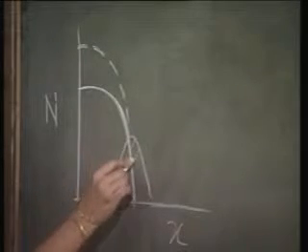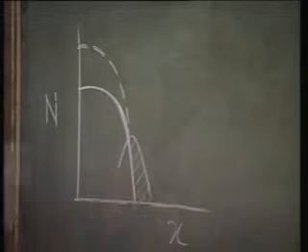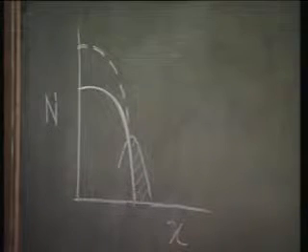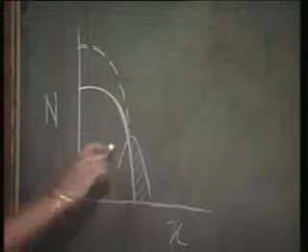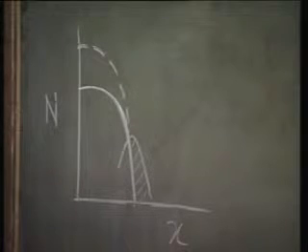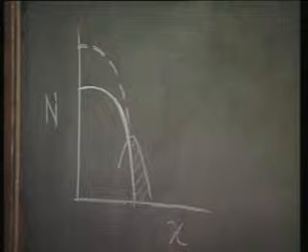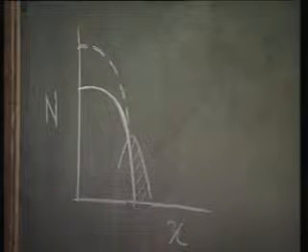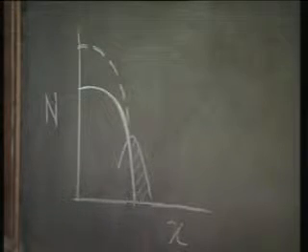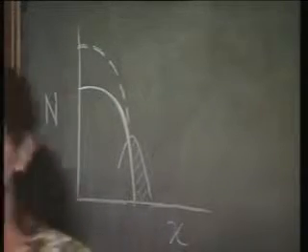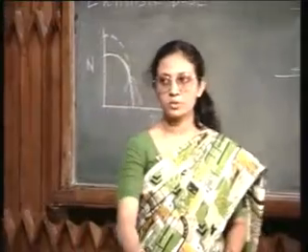So, this is actually the active base, immediately below the emitter, whereas as far as the extrinsic base is concerned, you are getting the full benefit of the doping concentration. This of course will give you a better control over the base depth as well as over the base doping concentration.